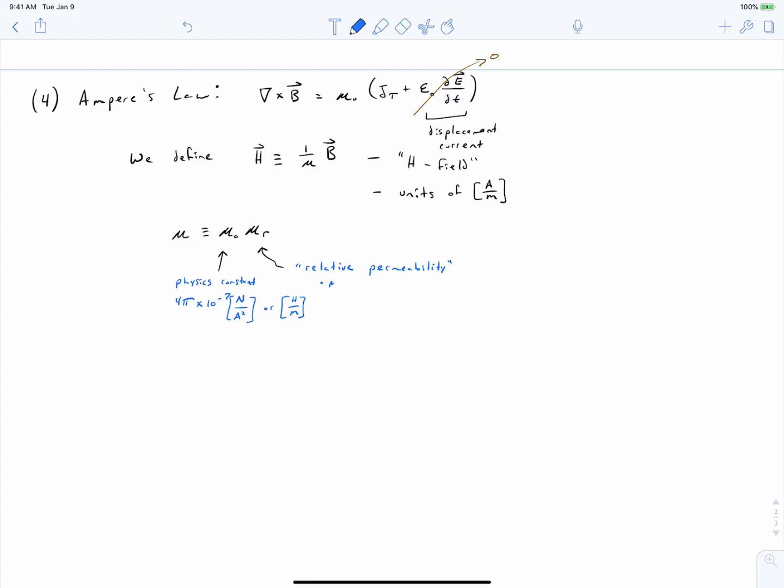In electric machines, we treat this as a material property that you'll actually have specified for you from your motor material manufacturer, from your steel manufacturer, in the form of a BH curve that will be provided to you. We'll talk about that more at the end of the lecture. And we'll just note that mu r is equal to 1 for a vacuum or air. So basically, in the air gap of our motors, we treat mu r as being 1. And in our steel, we treat it as having a value that we extract from the data sheet for the steel that we are using.